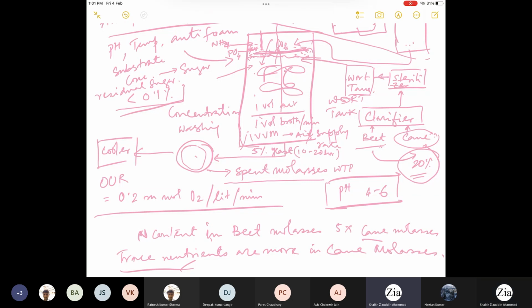But if you have a rotating system inside the reactor, cells very close to the stirrer will experience abrasion, while those that go away from the stirrer will not experience a similar kind of abrasion. Some organisms may experience shear stress that exceeds their tolerance limit, and in such cases you will have disruption of cells, but that amount will be very small.